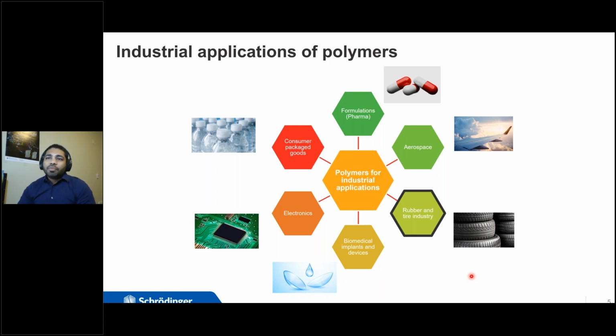It is taking time to make this technology mainstream because these new airless tires require a complete redesign of polymer chemistry. That is, we need polymers that have exceptional fatigue endurance, load-bearing capabilities, and creep and tear resistance. And on top of that, they also need to have strong adhesion to the metal surfaces of the vehicle.